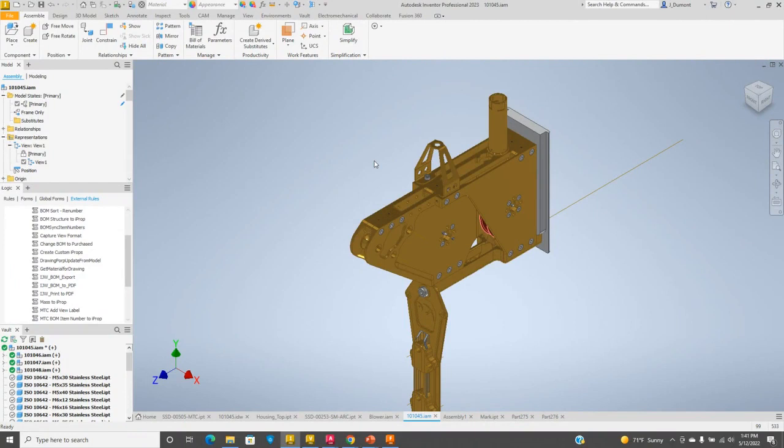Now, alternate V doesn't do anything. That is a new shortcut. It's really weird because it doesn't do anything. But what you can do is I can select multiple components, and then I can do alternate V, and all it's going to do is toggle the visibility off.